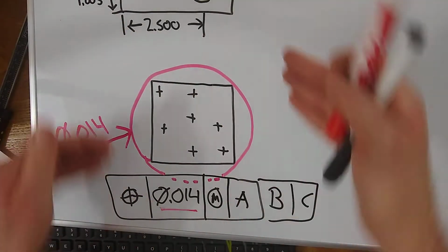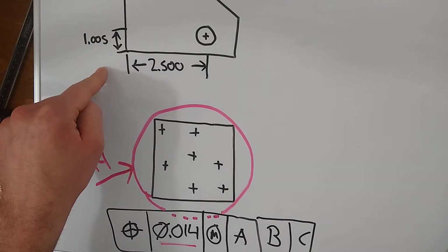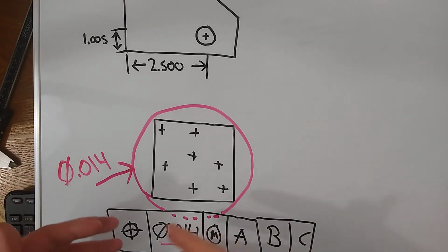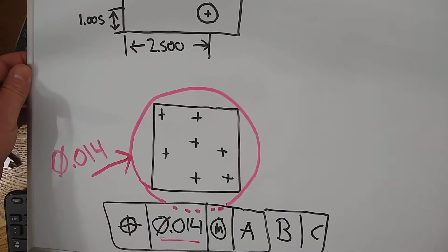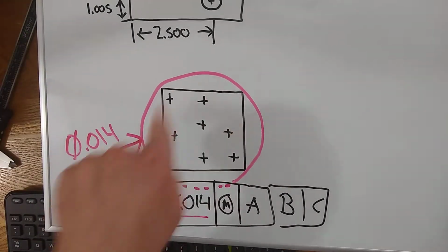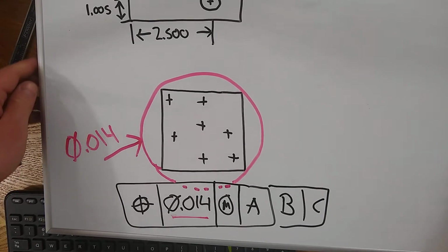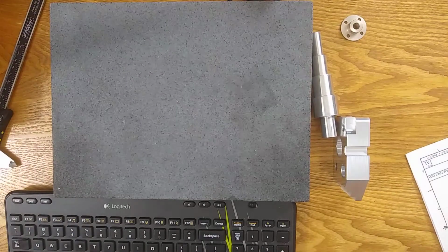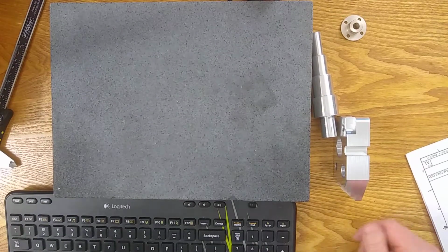If I wanted a circular tolerance zone using just my orthogonal XY, you can't do it. It's simply easier to develop these symbols and do it that way. So that's why GD&T came about, because this is more desirable. You get a bigger tolerance this way, and everybody's happier with a bigger tolerance, even engineering. So anyway, that's just one quick explanation on the position symbol in GD&T.